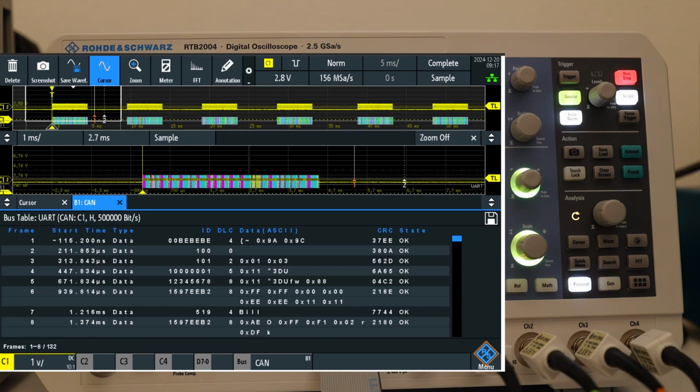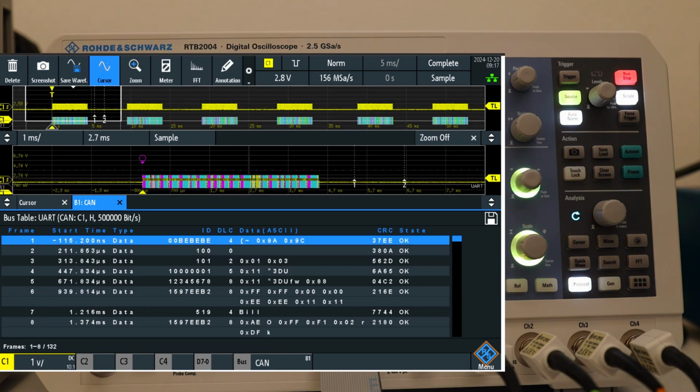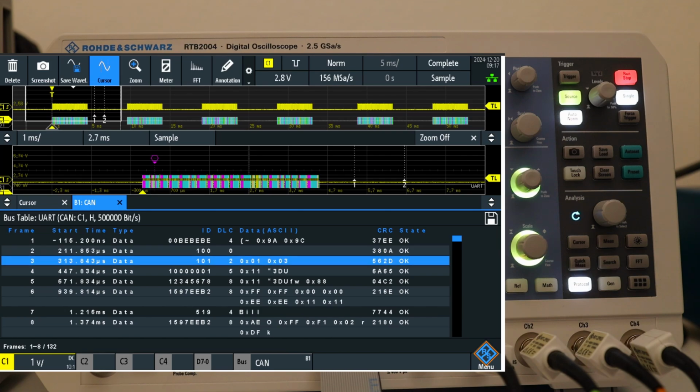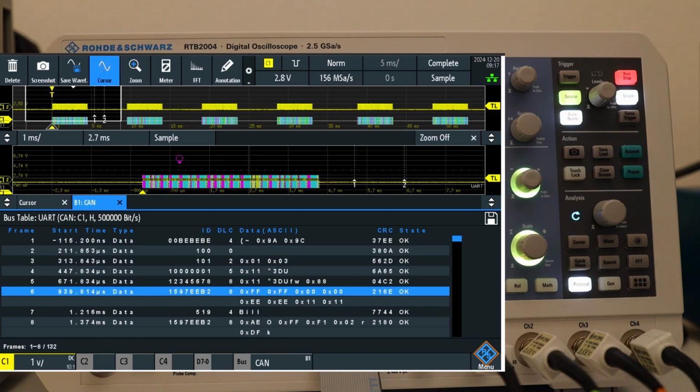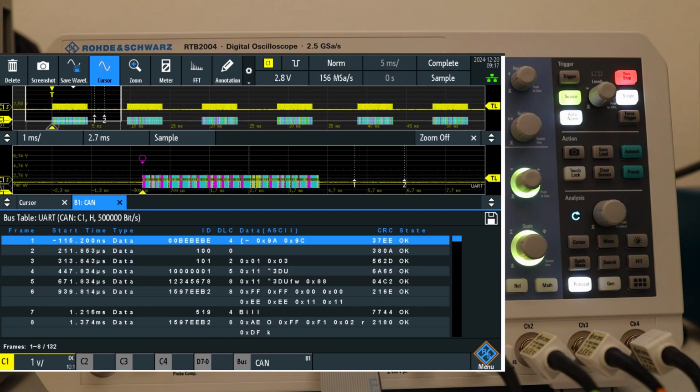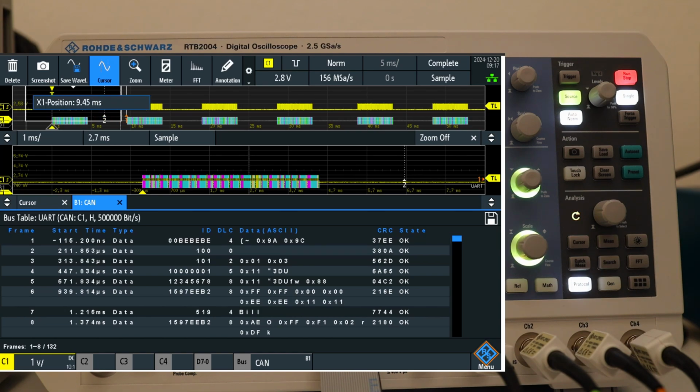This window shows you which packet you are looking at, so you can analyze every packet one by one, and there is a marker. When I select here, you see this little pink marker. This tells you which sub packet within the CAN frame you are marking. Okay, the pink marker is denoting that. So the first ID here came 00BE, and let's go to the next packet.